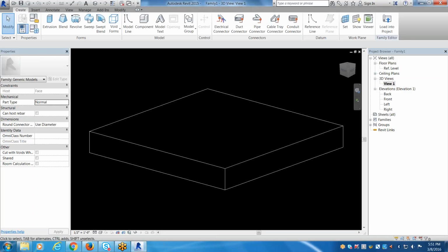They have that slight bevel. Yeah, we could do that. Now, how would that be done without using a void form? How would we do it? And I'll tell you why. Voids significantly decrease performance of Revit families, and when you place more of them, then your Revit project ultimately sucks.